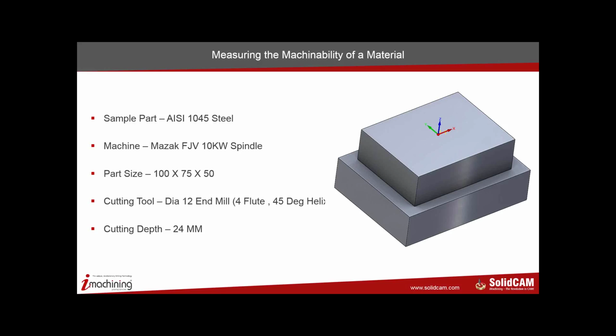We use a cutting tool. You could use practically any tool. You could use 10, 12, 16, anything. We are using a 12 diameter with 4 flute and 45-degree helix, and the depth of cut is about 24 millimeters, the actual depth of cut.